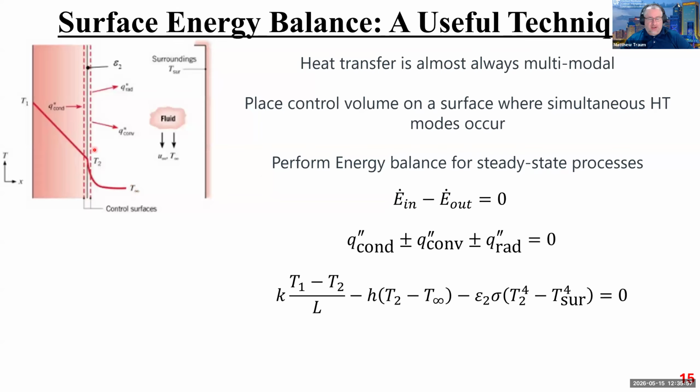And so once we've got this control volume, then we're going to perform an energy balance, just like you've done in thermo thousands of times. In a steady state situation, the change in energy with respect to time is zero for the system, right? Which of course is also true if the system has no mass because it can't store any energy. And so all of the energy flux into your control volume minus all of the energy flux out of your control volume has to equal zero. There's no opportunity for storage.